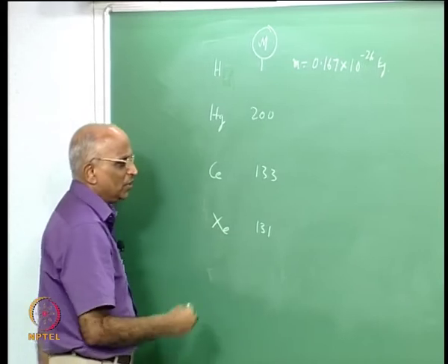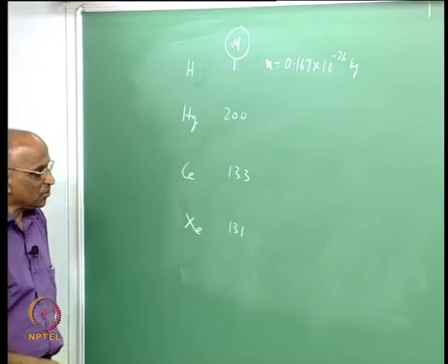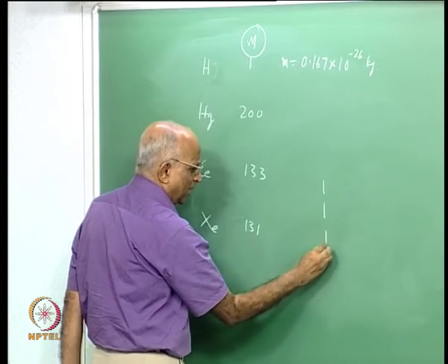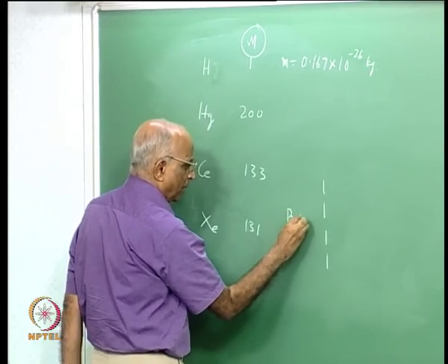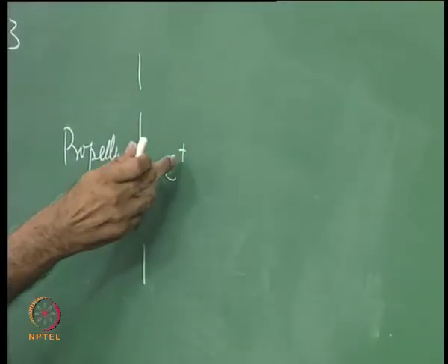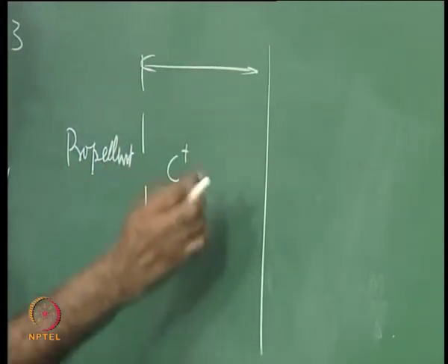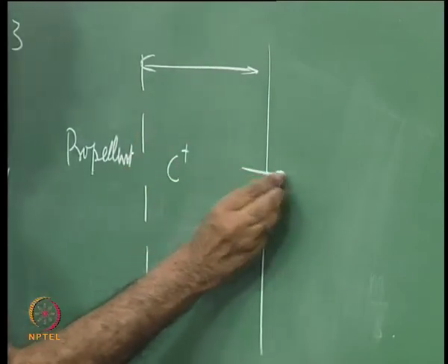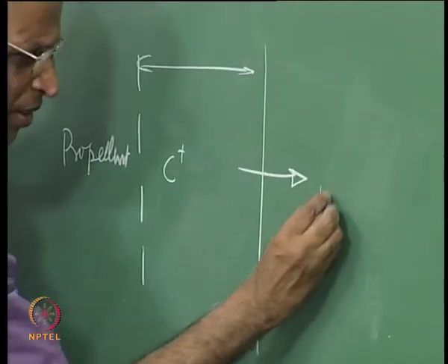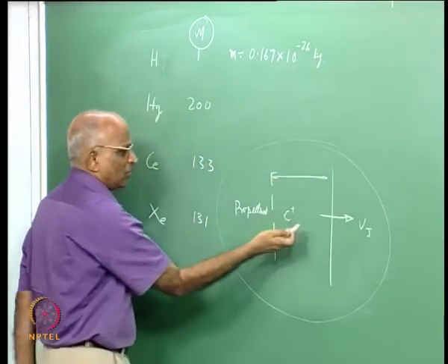We have still not described what the propulsion system will comprise of, but more or less I have to first take a substance like a propellant, convert the propellant into gas or make it charged in some way, then put a field over here, that means a potential difference which will give it a velocity, and maybe put such a potential difference that I get a high jet velocity, and this is what gives me something like an electrostatic propulsion.